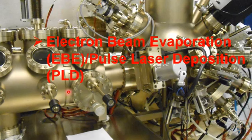at a smaller vacuum. Though vacuum is created inside the reaction chamber in those techniques, it is less than in molecular beam epitaxy, and due to this, there is a possibility of impurity. Though this technique is advantageous over molecular beam epitaxy in terms of cost, the film deposited with this technique is less pure as compared to the film deposited via molecular beam epitaxy.